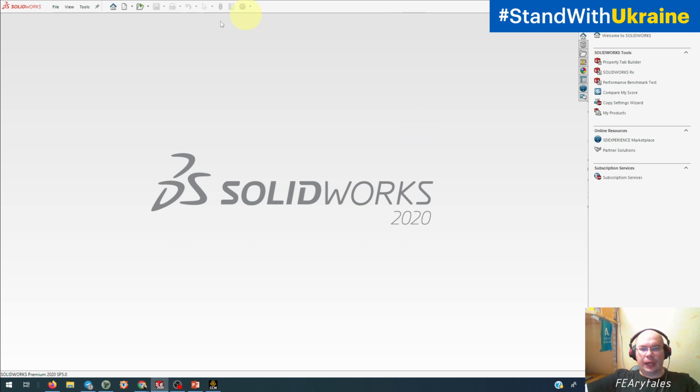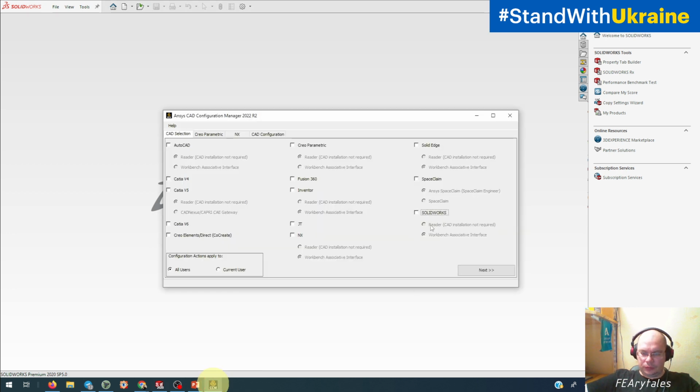So, for example, I have SolidWorks 2020 and I have configured integration with SolidWorks for showing some things that I do during this video. And if I try to open a model from SolidWorks 2021 or 2022 or even the last 2023, I will not have this possibility. To open a SolidWorks model from SolidWorks 2021, I need to open this CAD configuration, select this one, change to reader, reconfigure, and then I will have the possibility to open.